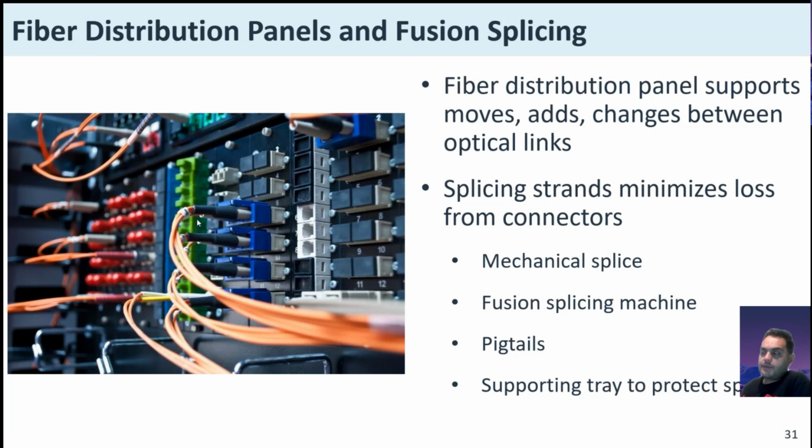Of course, we see here with the fiber optic cable, using connectors does reduce overall performance of the cable. Each connector will cost a certain amount of insertion loss, typically budgeted as half a decibel, and reflection loss. Consequently, in some circumstances, it may be preferable to splice two cables together, either to repair damage or to extend the cable run. Cables can be spliced mechanically using an adhesive junction box containing index matching fluid that ensures a continuous path between the two strands. A fusion splicer achieves a more permanent join with lower insertion loss at about 1/10 of a decibel.